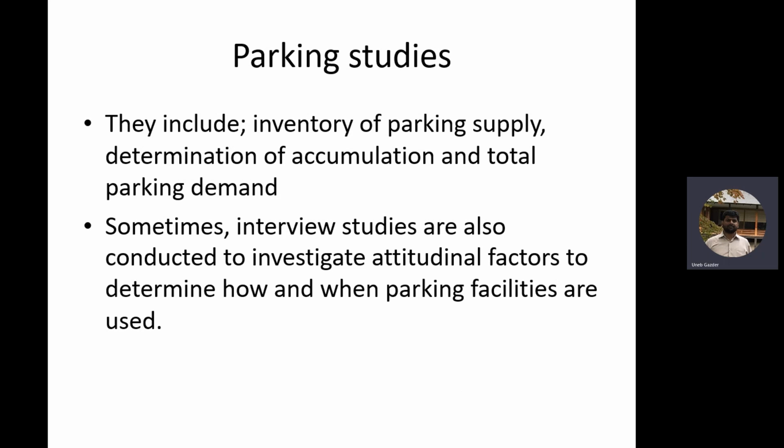So through parking study, we try to find out these three things: capacity, average duration, and accumulation of vehicles in the parking area at particular times. In some cases, we may do interview studies to know the behavior of the driver. Why he is coming, why he is parking at this spot, why not some other spot, and so on. Okay, so interview studies are mainly done to know the behavior of the driver.